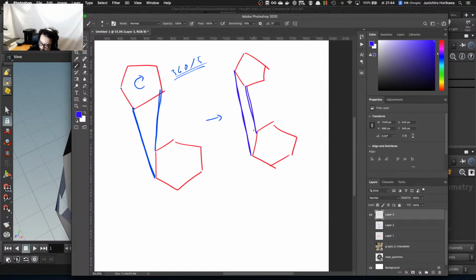And then after having this, I can finally resample this blue line using some resample node or something. Then after resampling it, I could deform each line using some kind of force vector, something like this, and then create a mesh using a node like loft or skin.